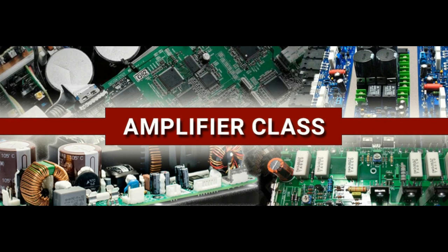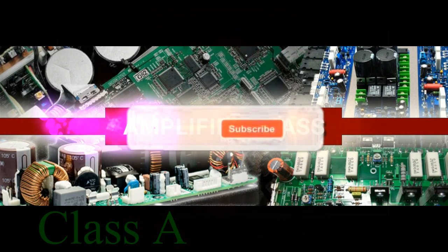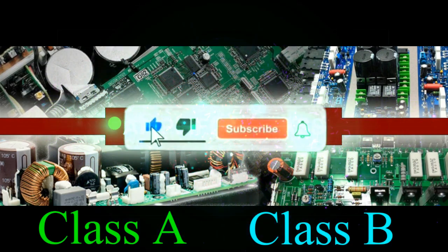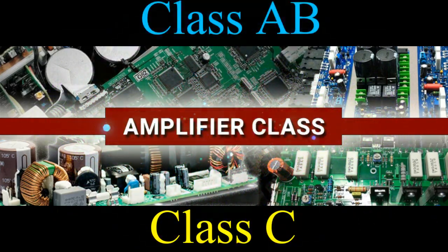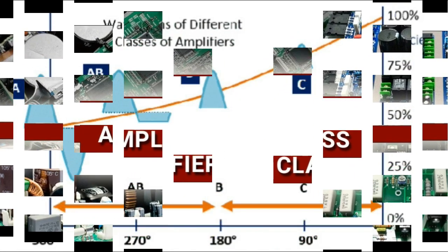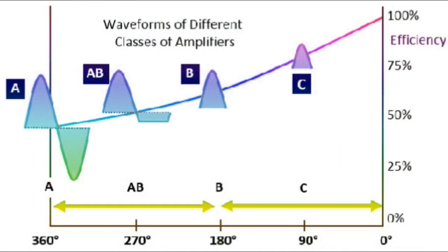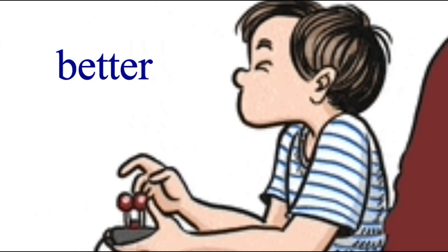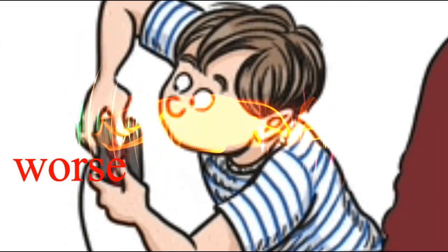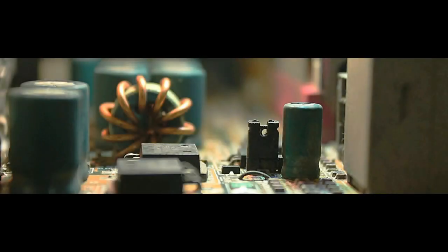Audio power amplifiers are classified alphabetically into Class A, Class B, Class C, Class AB, etc., based on circuit configuration and operating mode. These classes range from low-efficiency near-linear output to high-efficiency non-linear output. None of the amplifiers is better or worse than the other and each has a specific use depending on the need. Each of the different classes of amplifiers has a certain maximum efficiency.